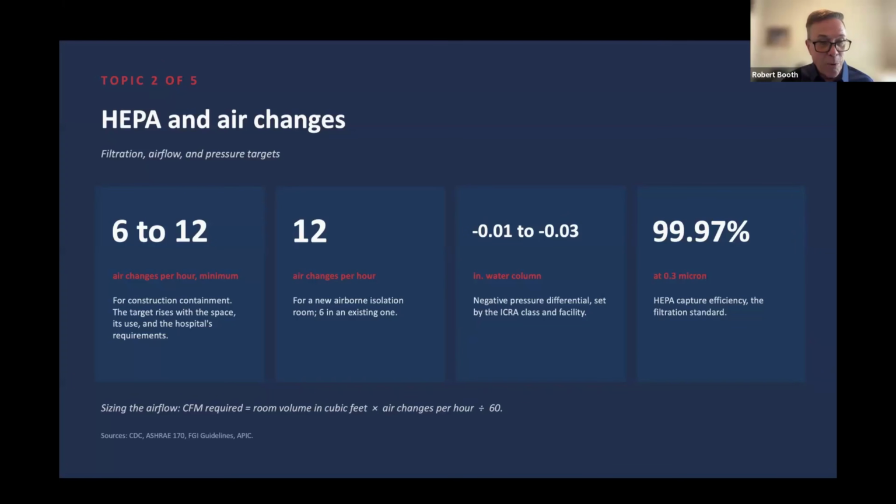I will tell you, I get a little pushback every once in a while, and some of my colleagues are like, we're never going to have HEPA filtration. That's not achievable. I disagree. It is at the beginning. And what we want you to do is look at the whole system and make sure that you get an achievable drop before you start construction. So the importance here is when you set these things up, you should measure at the intake of the device and where you're exhausting it to, and make sure that you get a good reduction.